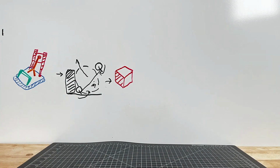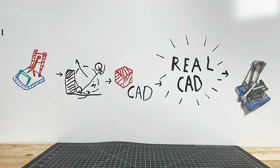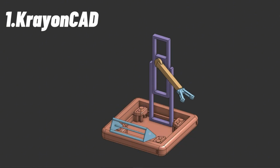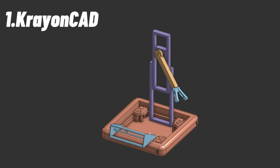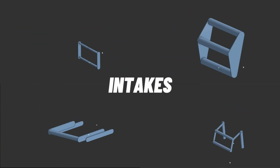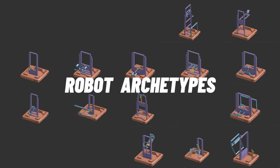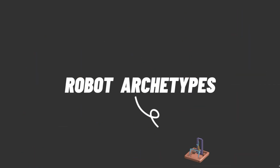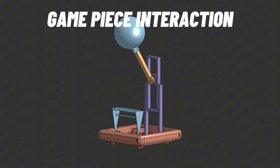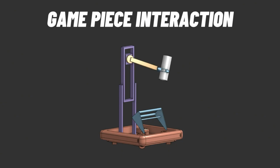I'm going to walk you through the 5 steps of the design process, the same process I used to design this robot. Step 1, Create CAD! This is our fast idea phase in CAD, where we quickly model mechanisms like intakes, elevators, or manipulators, which we piece together to make as many robot archetypes as we can. Then create a pros and cons catalog that gradually narrows our options until we arrive at the robot we want. Our final current CAD robot featured a 360-degree arm, a ground intake for coral, and a dual-purpose claw for algae.